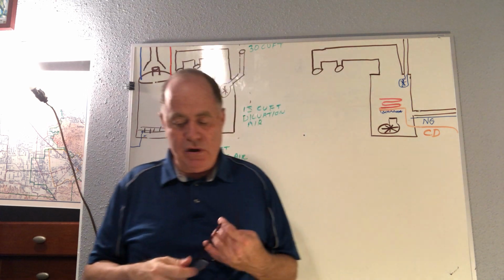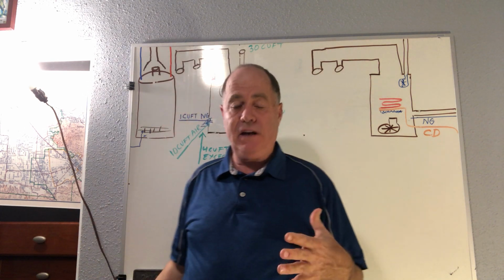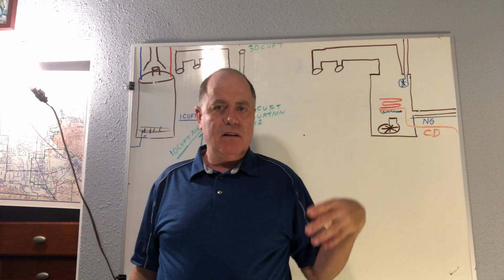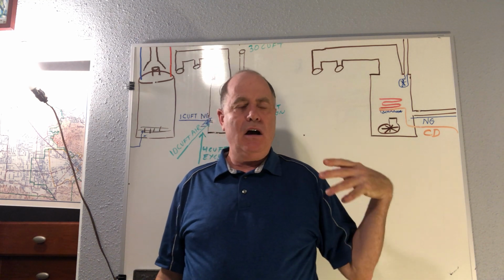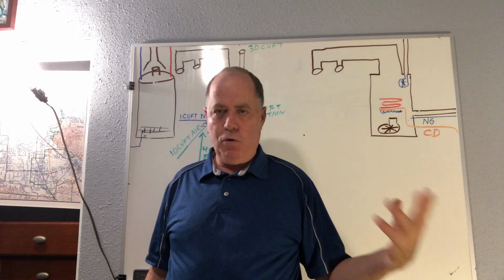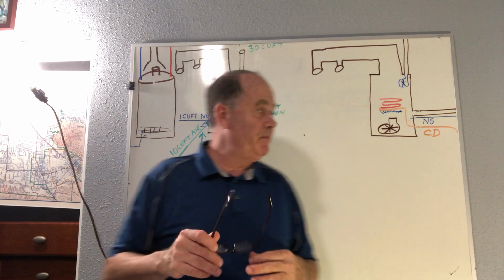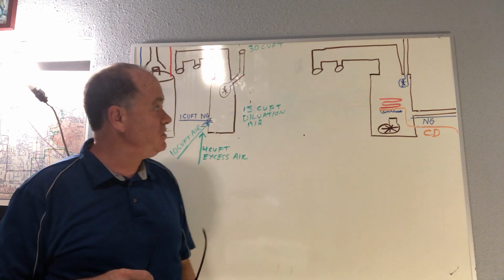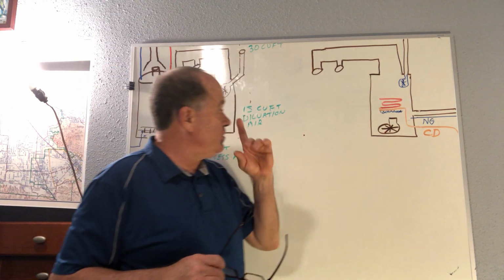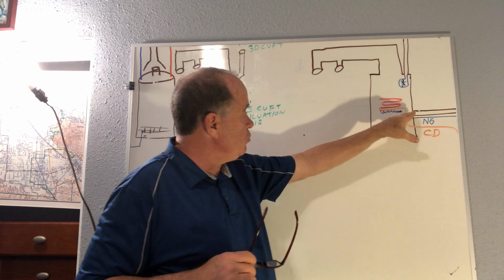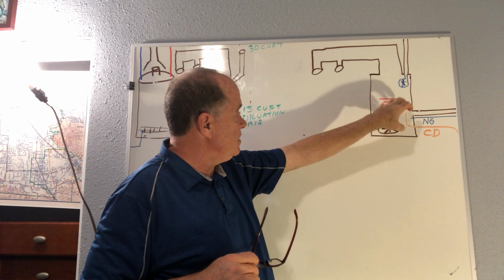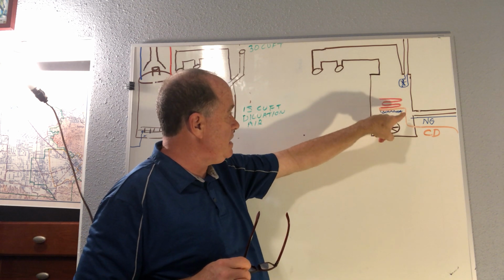So, anyways, if you start starving any heating appliance, the flame turns yellow, you get a lot of blackening of everything, you produce carbon monoxide, which is poisonous, etc. Back to our high efficiency furnace now, and the concept is you've got the air that comes in, and then the natural gas mixes and heats up, makes a fire and then heats up a heat exchanger.